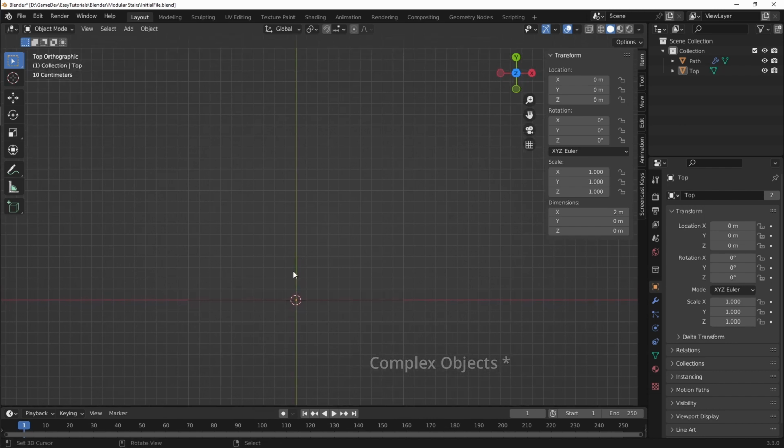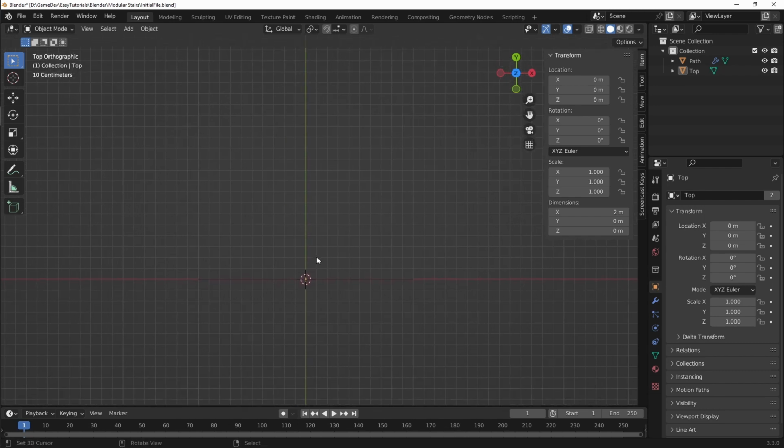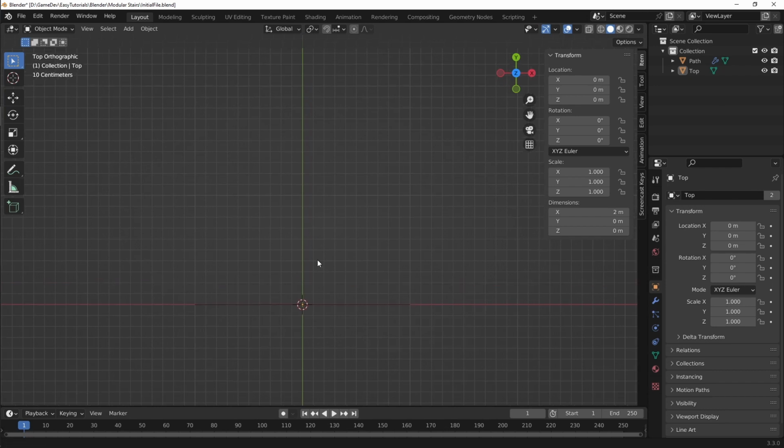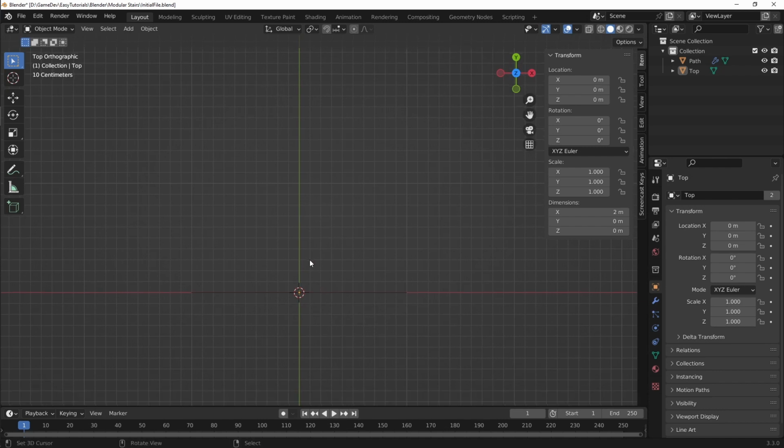So what we're going to do to counter that is build all the parts of the pathway separately, so that we can then join them finally inside geometry nodes. We won't be creating the whole profile in a single object. That will also help us in obtaining separate UV mappings for each part of the path.